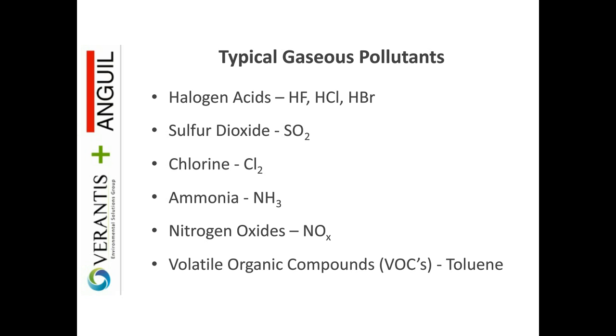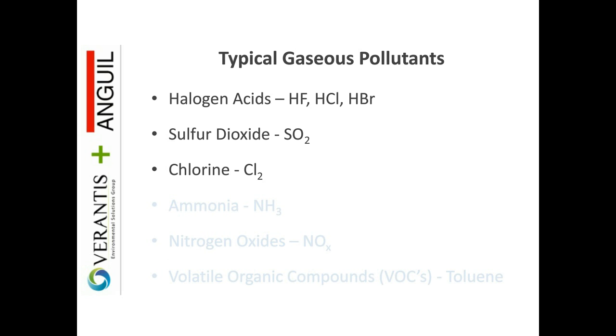Those would be definitively thermal oxidation problems. As we move through a thermal oxidizer, we're going to end up with compounds like HF, HCl, HBr, SOx, which often manifest themselves primarily as SO2 as far as our wet scrubbers are concerned, and chlorine, bromine, and related compounds.